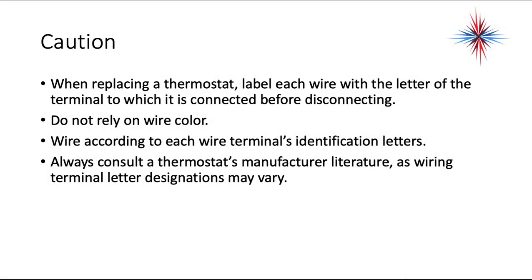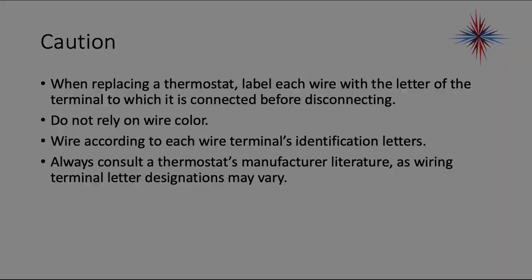When replacing a thermostat, don't trust the wire colors. Label each wire with the letter of the terminal. Okay? Heat pumps have a number of additional wires that you don't see in straight air conditioning. Wire according to each wire terminal's identification letters. Always look at the thermostat literature such as wiring or terminal designations because the wiring may vary.